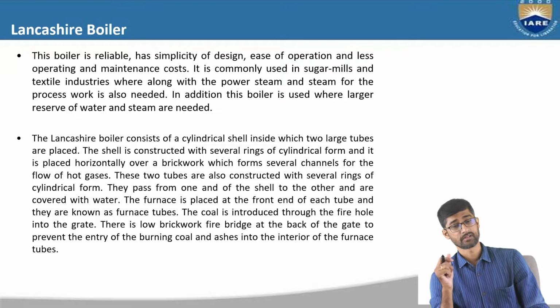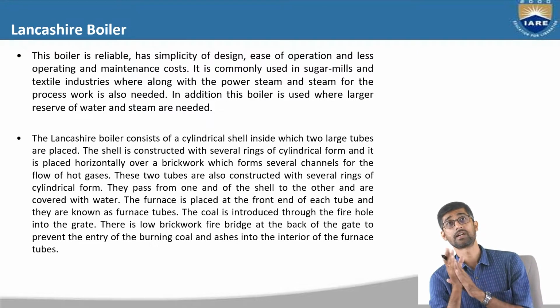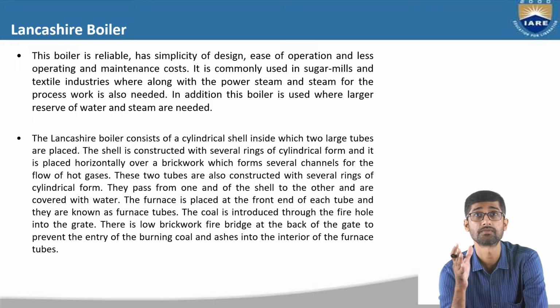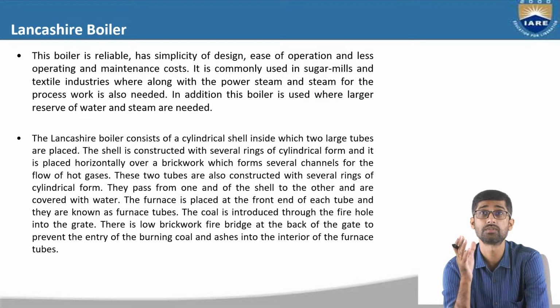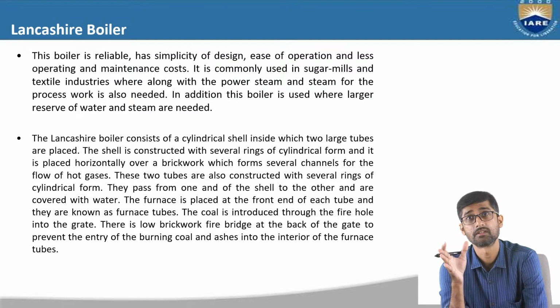And this Lancashire boiler also consists of a cylindrical shell inside which two large tubes are placed, right? The shell is constructed with several rings of cylindrical form, and it is placed horizontally over the brickwork, which forms several channels for the flow of hot gases. These two tubes are also constructed with several rings of cylindrical form. They pass from one end of the shell to the other end and are covered with water.